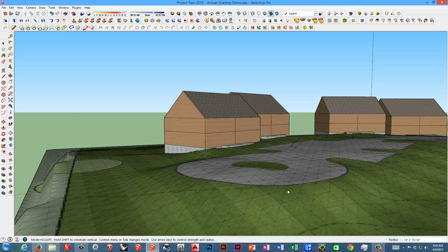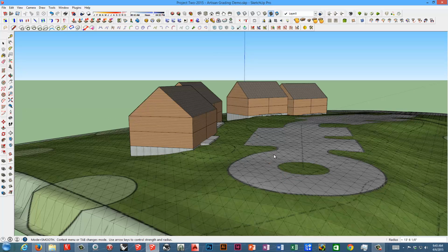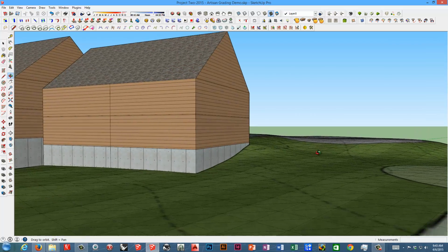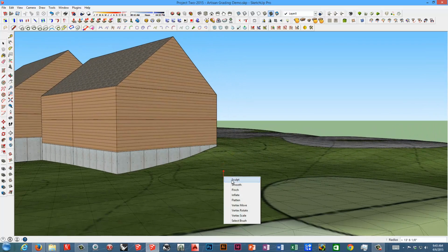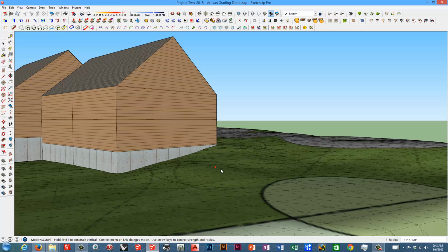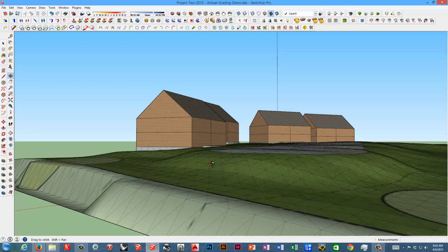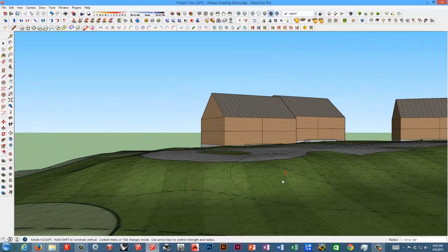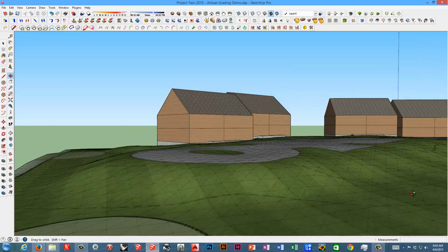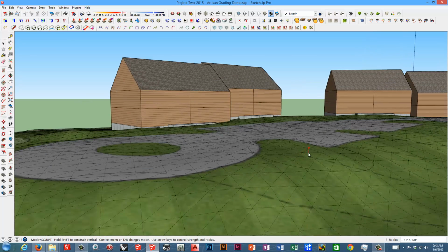And because I have the image on there, I'm basically just looking at the image. When I get that perspective correct, when you see the lines kind of smoothing out a little bit, then you know. So now you can see I can come in here and just kind of level this off a little bit. I've got kind of a swale dropping across through there, but might want to pull that up a little bit. Switch to sculpt. Okay, that's looking a little bit better. Again, the idea is that this isn't going to be perfect, but it's going to give you a good idea. Looks like I maybe need to pull that up a little bit more so that's not falling off the side.